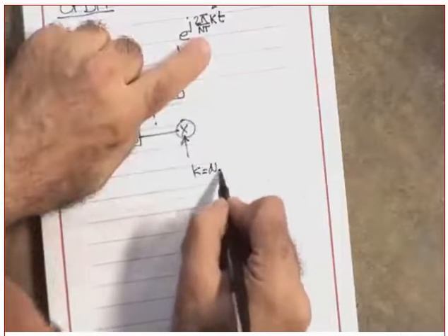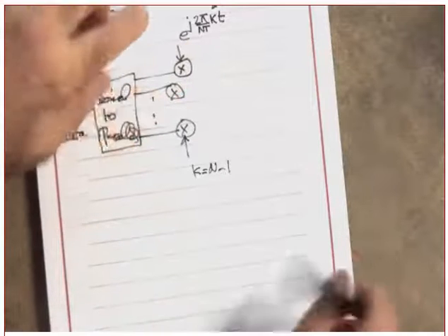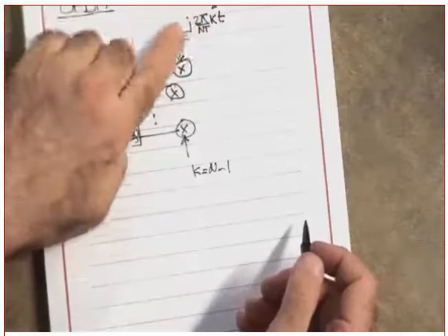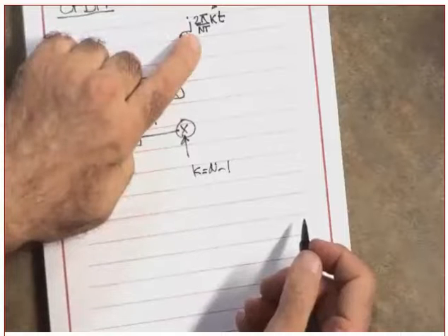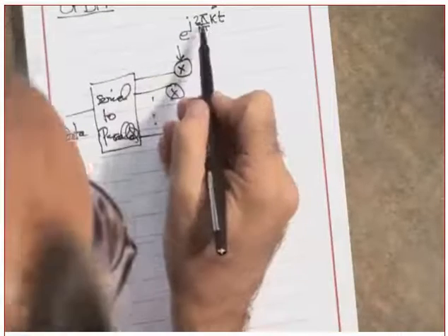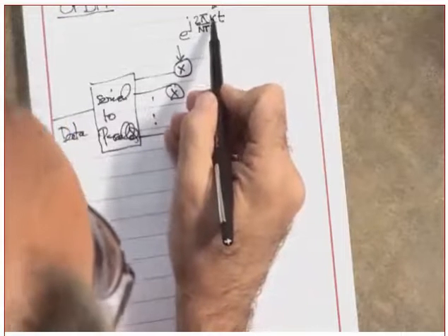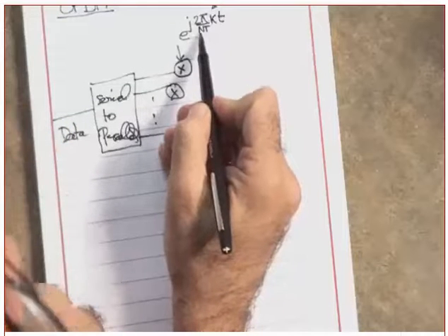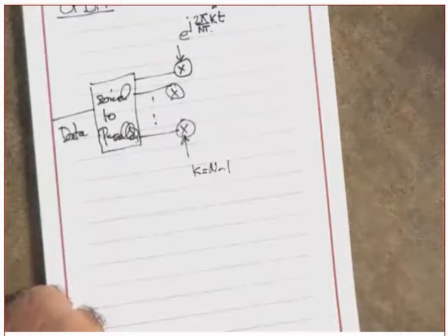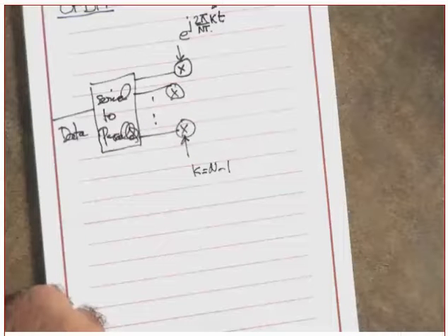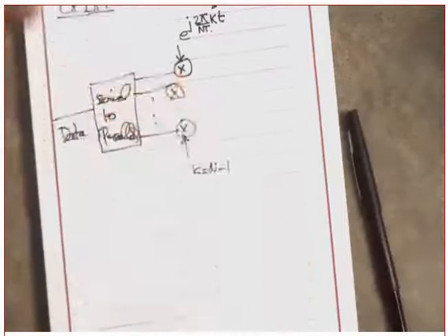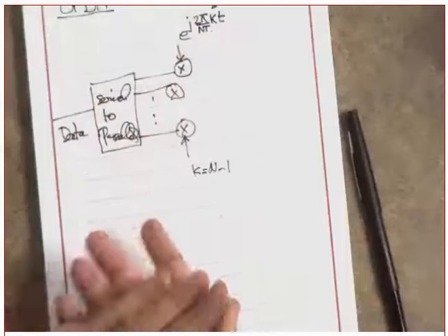Here, what is the k? N minus 1. What is the separation, by the way, between the frequencies? Can you tell me? You are losing me here. Now remember, the frequency is 2 pi f. So the f is k over N t, where k equals 0, 1. In other words, 1 over N t. The other one is 2 over N t. So what is the separation between them? 1 over N t, where N is the number of subcarriers. Did you get this or not?